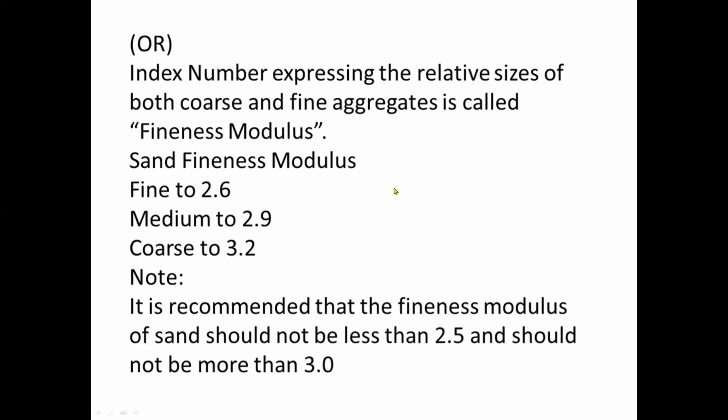The sand fineness modulus is fine at 2.6, medium at 2.9, and coarse at 3.2. It is recommended that the fineness modulus of sand should not be less than 2.5 and should not be more than 3.